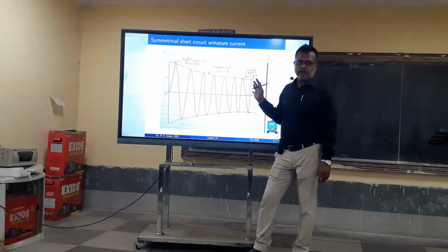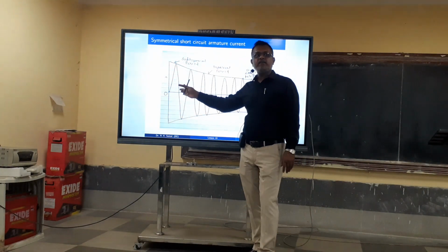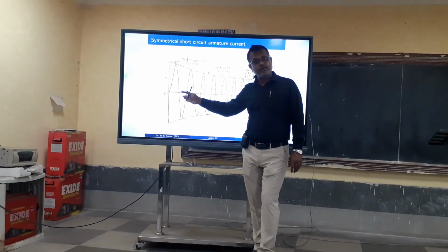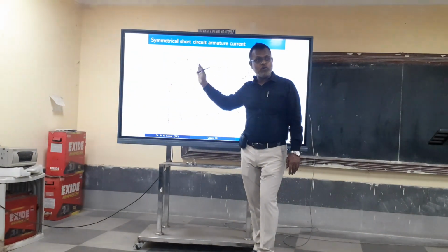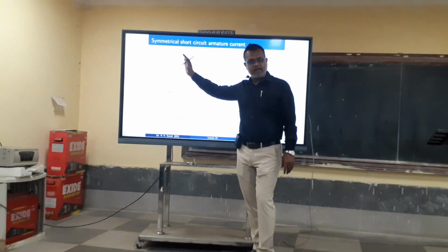Now based on this, what can you infer? You can infer that initially the impedance of the alternator is very low, because the current is very high. Initially the short circuit current is very high.